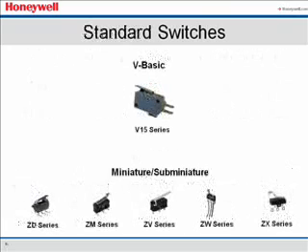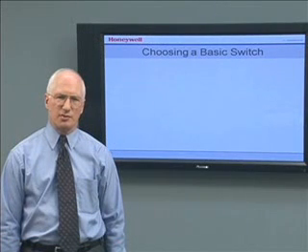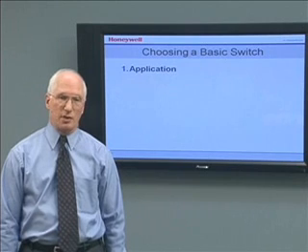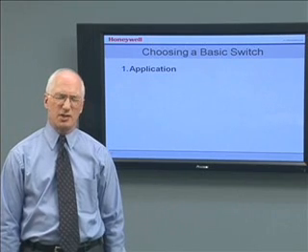Honeywell standard switches are designed with the same high quality as our premium switches, but for applications where the cost of failure is low. It is important to choose the right kind of switch for the requirements of the application. There are 5 things you should consider when choosing a MicroSwitch basic switch. Application. What size do you need? Does the switch need to be hermetically or environmentally sealed? Does the application require a premium or standard switch?